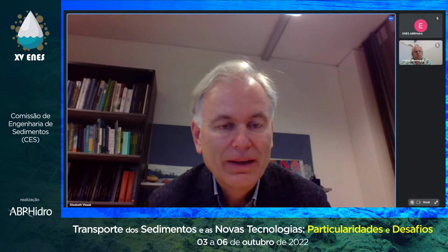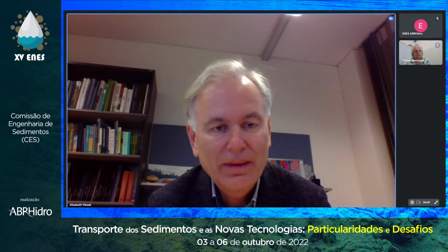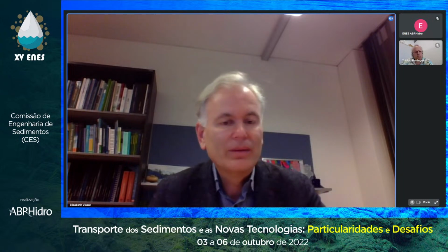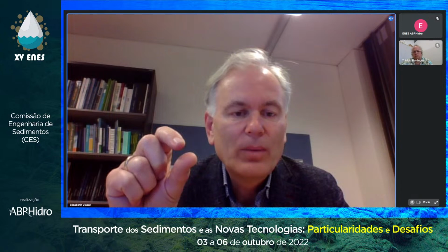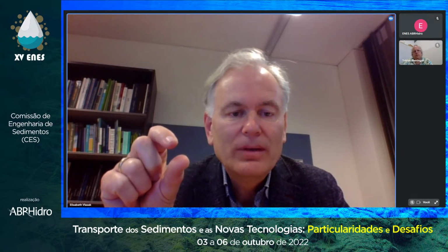That's a very, very important point. In principle, we have to differentiate the coarse material from the fine material. When it comes to the fine material, let's say smaller than 1 millimeter, suspended sediments mainly, then we have to look into different processes. One is the concentration. In our country, people say that if you increase the concentration to more than 1 gram per liter, they would ask you to stop the flushing. So you have to monitor the sediment concentration downstream with a turbidity sensor, with probes, whatever you have, with an ADCP additionally.